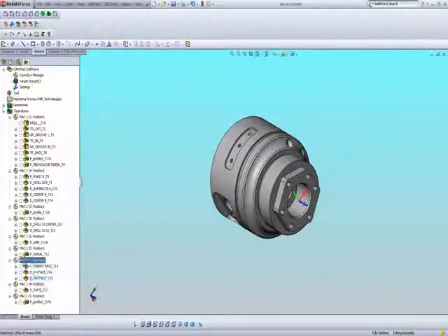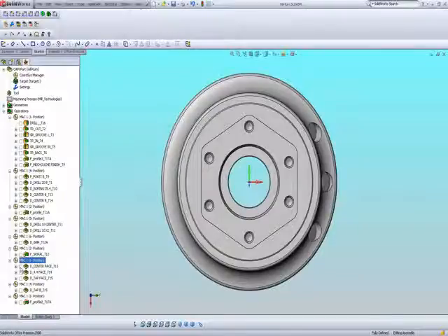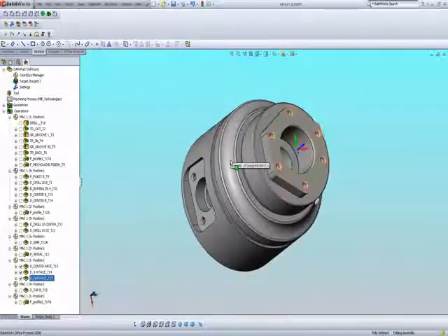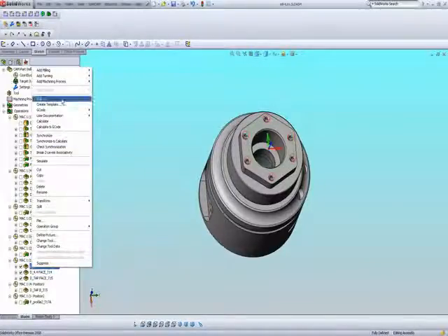Again, I'll have my Mach position 1 and position 1 itself, just like in my drilling, just like in my turning. I can go back and forth, use it whenever I want to, as seen over here. And then I'll use my simple drilling operations. Drilling the first hole over there, the second one, and the next one, as seen over here. All this done, Mach 1, position 1, simple drilling operations.